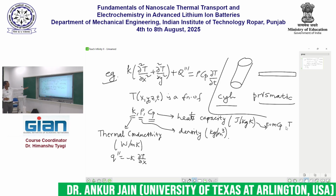In the context of lithium-ion cells, we are interested in understanding what are the values of K, rho and Cp for the cells. Keep in mind also that while the heat capacity is just one single valued quantity, thermal conductivity may be anisotropic.